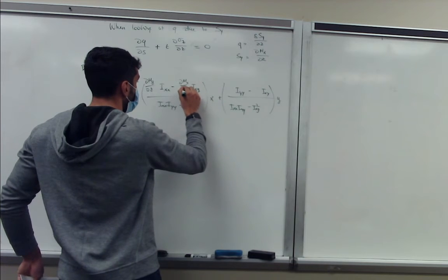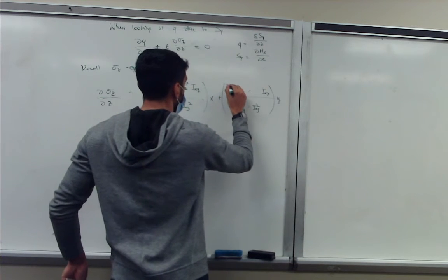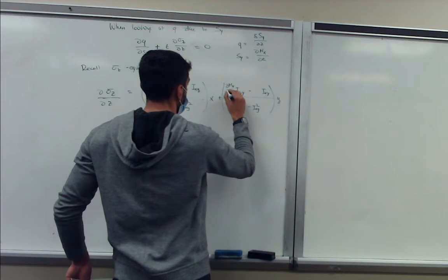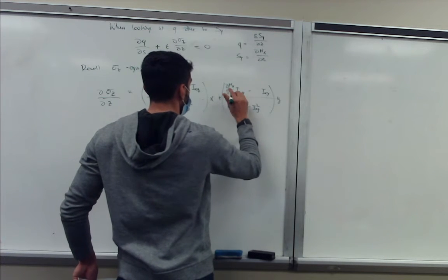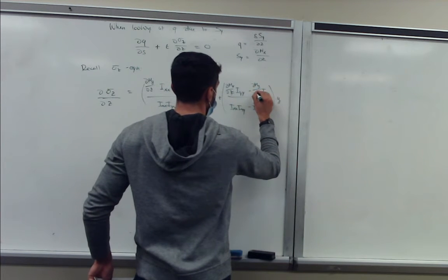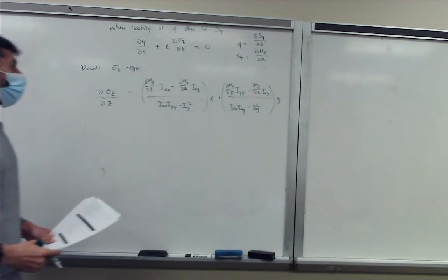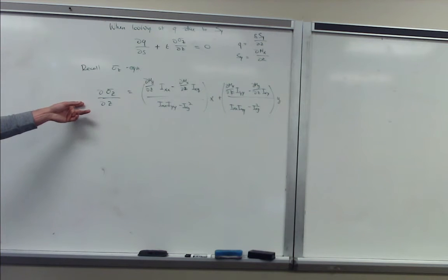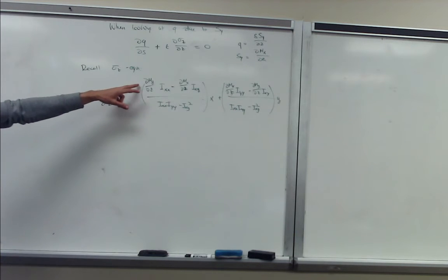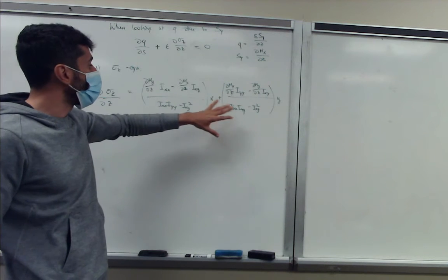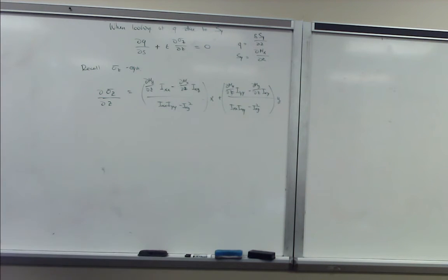Mx with respect to z, and My with respect to z, because that's the only thing that can vary as a function of z. So the variation of direct stress with z depends on the variation of the moments with respect to z, and of course the remaining moment of inertia terms.